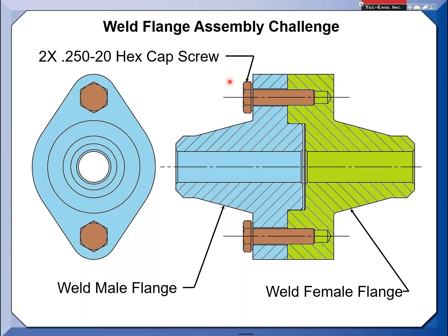I can't tell you how many times I've heard, I can't get the bolt in the hole, or you cross thread down here when you put the bolt in, because we didn't do the due diligence in engineering to prove out mathematically this would go together if the parts were compliant to the engineering drawings. I've had parts come in compliant to the drawings, but since we didn't do the due diligence and didn't ask the right questions, it wouldn't assemble. That's the overall point of all these exercises.